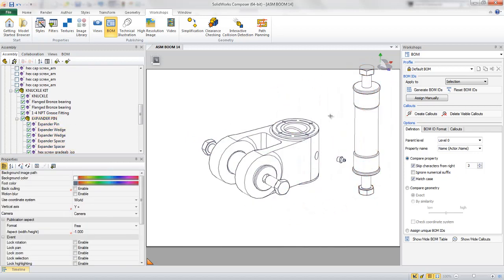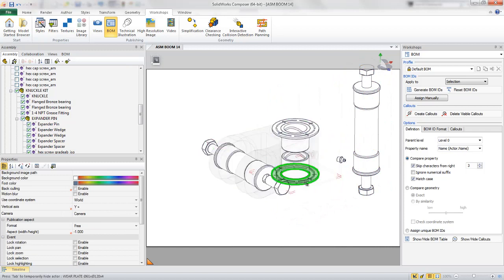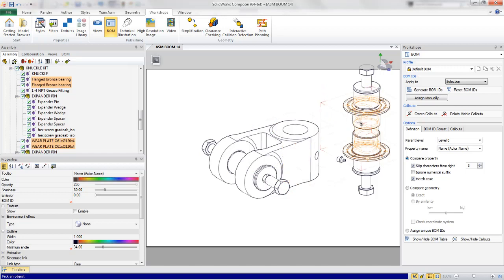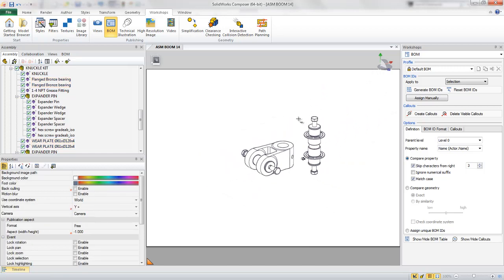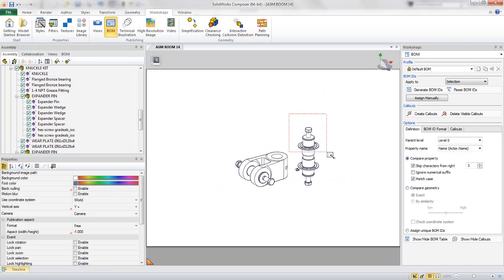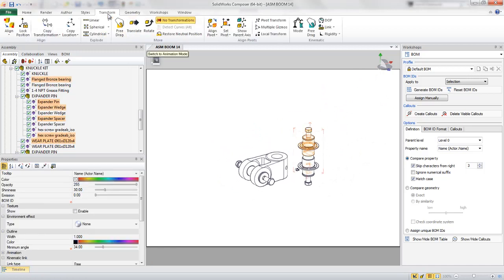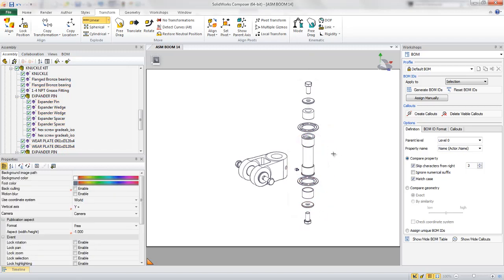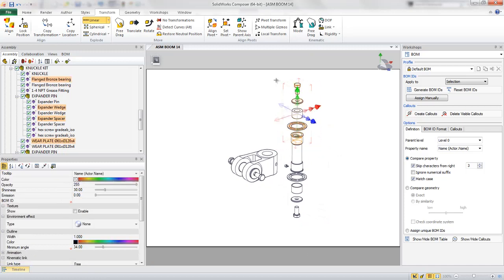Now sometimes we move components and we don't get everything we're after. Another great tool for this is to transform based on the position of another component. And make sure that if we miss anything, we can always go back and make changes. Now let's take a deeper dive and look at some more advanced tools for doing these procedures. On the Transform tab, we have a tool that allows us to quickly do linear explodes. All we need to do is select a series of components, and the components are spaced evenly apart.